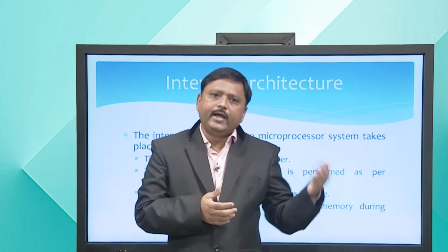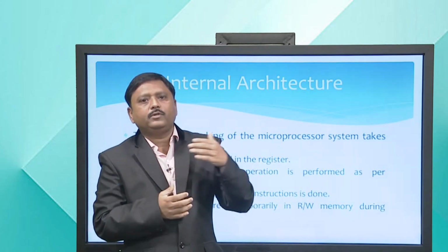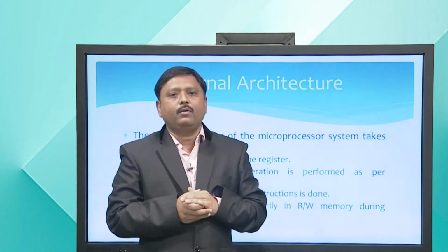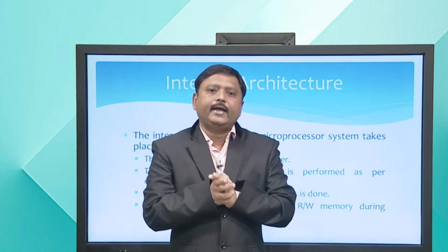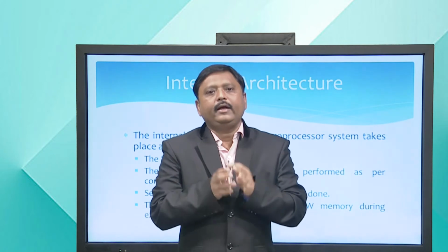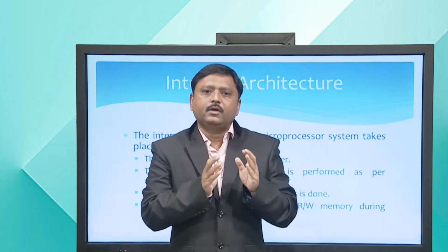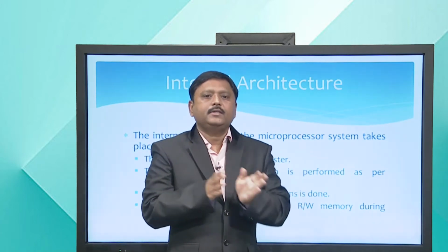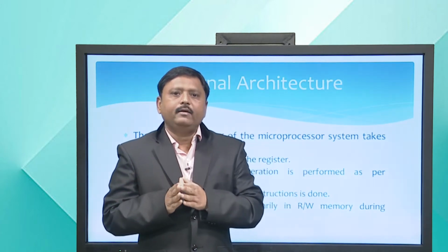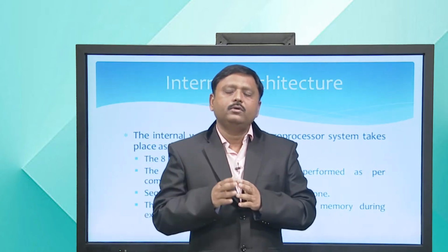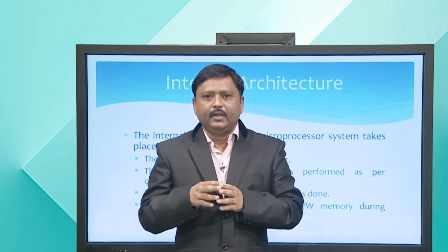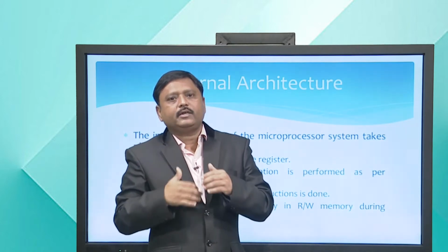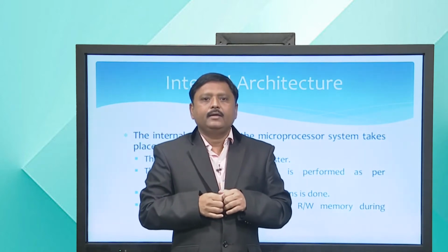During the entire process, the microprocessor uses the system bus to fetch the binary instruction and data from memory. It stores data in general purpose registers temporarily. It performs computing using the ALU, and finally, it sends out the result in binary using the system bus to the 7 segment LED display. Now, how it works, let us try to understand step by step.